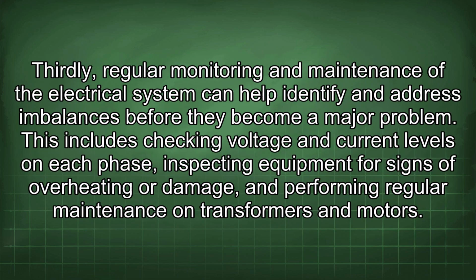Thirdly, regular monitoring and maintenance of the electrical system can help identify and address imbalances before they become a major problem. This includes checking voltage and current levels on each phase, inspecting equipment for signs of overheating or damage, and performing regular maintenance on transformers and motors.